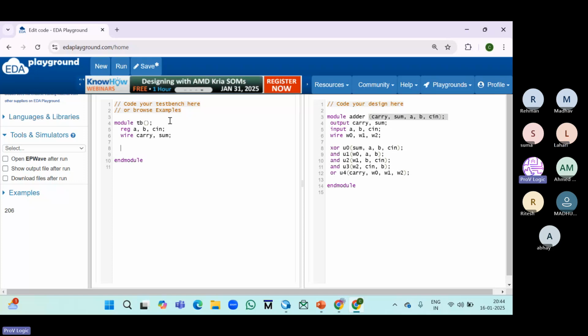Why should the output be declared as wire data type? Even in registers, counters, or sequential logic circuits, we follow the same. Outputs must be declared as wire. In the test bench, inputs must be declared as reg. Why? Maybe we need to store the input, so in our flow, whenever we call our input variable, it can remember. So we are using a register to store it. Is that correct, ma'am? How many of you have an idea about procedural assignment statements and continuous assignment statements?